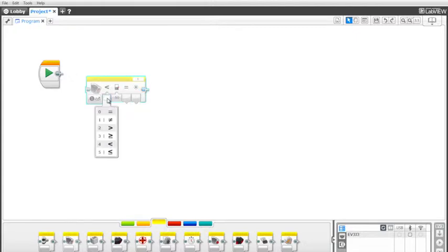Okay, so you can specify equal to, less than, not equal to, all these comparing functions, and specify the threshold. Here you just measure the reflected light intensity, and if it's less than 50, then it will return true. This true value can be used to pipe into other blocks that need this condition, and at the same time it will output the actual reflected light value, whatever it is, it will tell you. Okay, so that's color sensor.